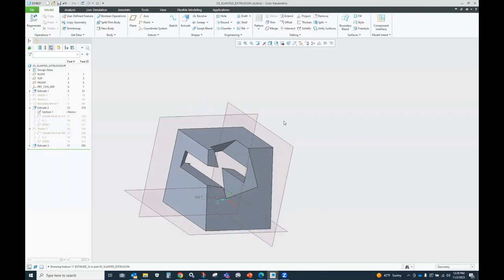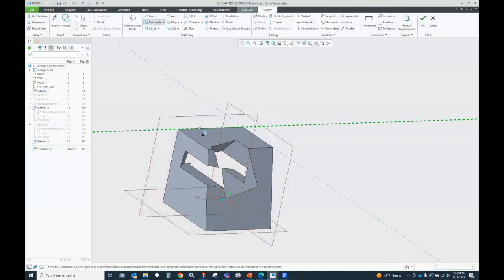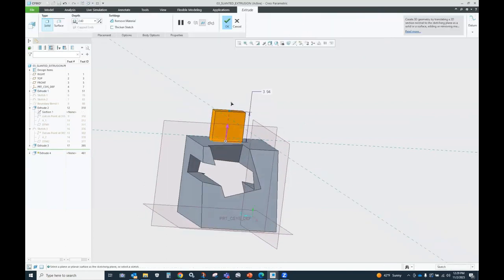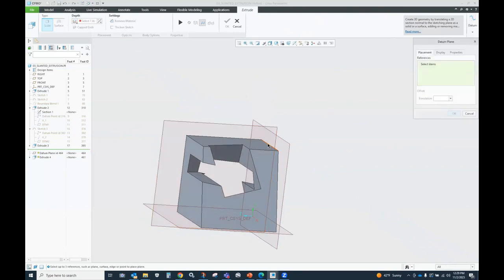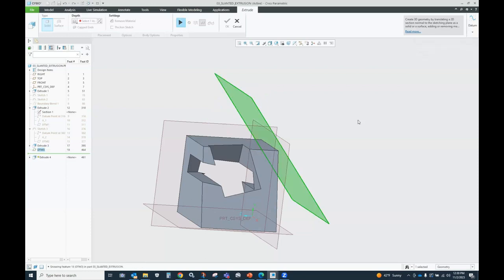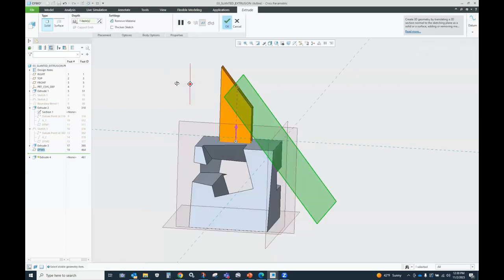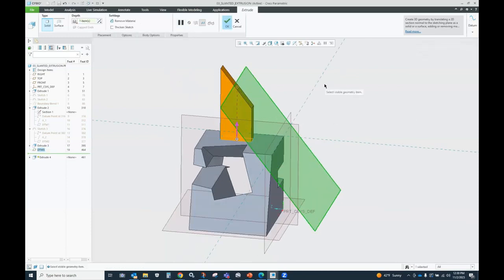So if I wanted to extrude from here, some shape, and then I want that to end at a datum plane, I'm going to say to reference, and then I'm going to create that datum plane right now. Maybe it's through that edge and at an angle, and then we'll rotate that up. So I can certainly do that as my reference, either before or after the feature.